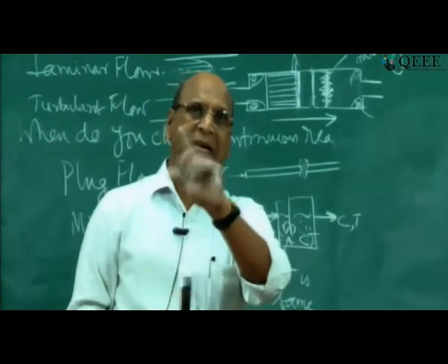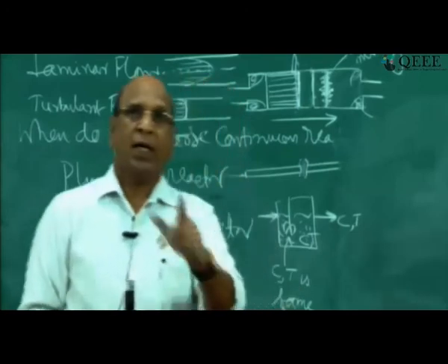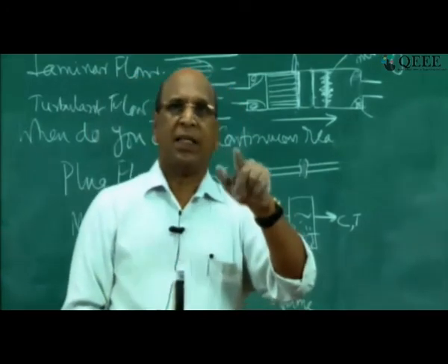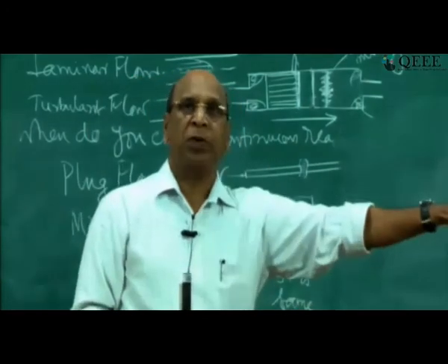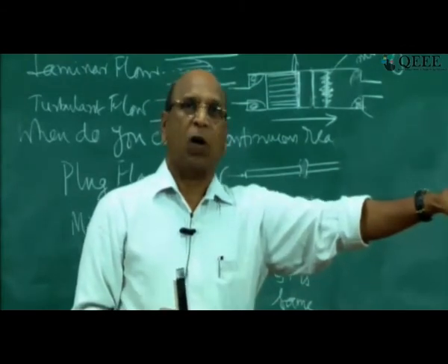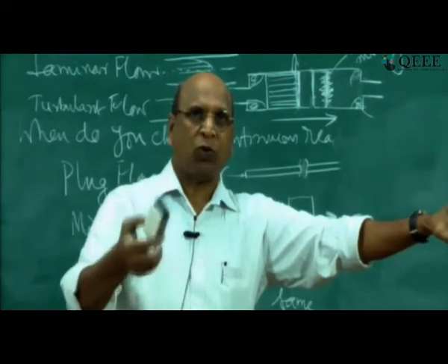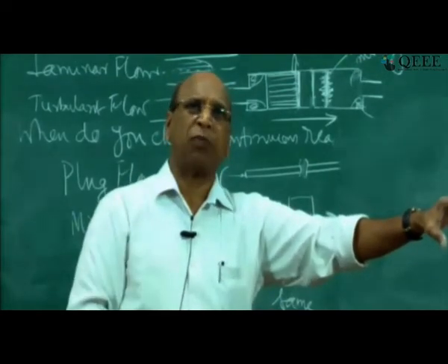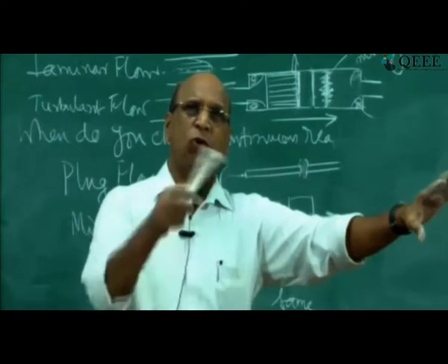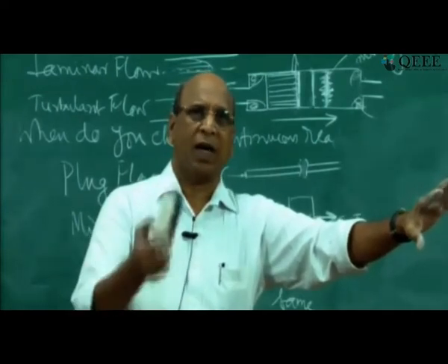So that's why those things have to be taken into account for gas phase reactions. For liquid phase reactions, we don't have to take it into account, but now you should design a pump for the pressure drop. That's why you calculate pressure drop in pipes and the friction factor. Why do you calculate the friction factor? It is not just an exercise to solve a problem in class.